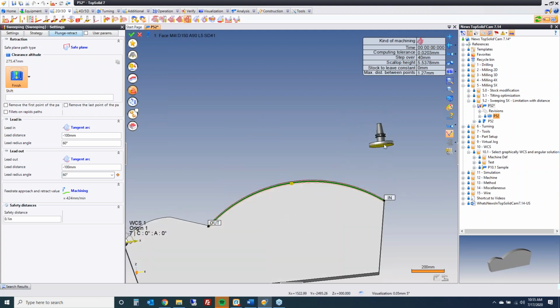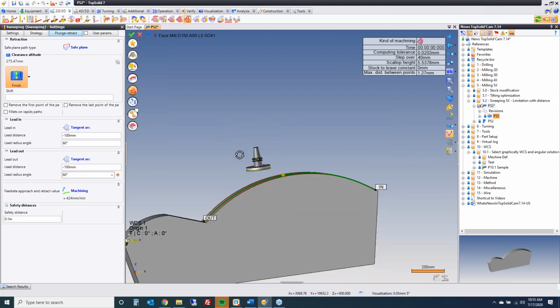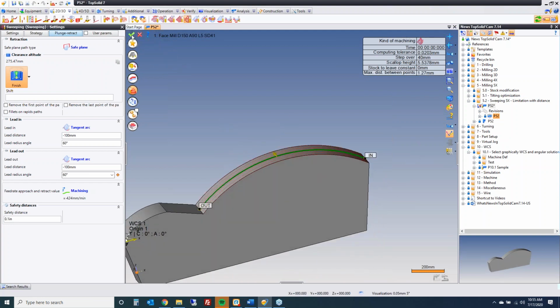Let me float this way. Come on tangently this way, so you ease the tool in, and then you cut, because if you came in tangently this way, you would over travel the machine, for example. So that's step one. Let's just have a look at that.